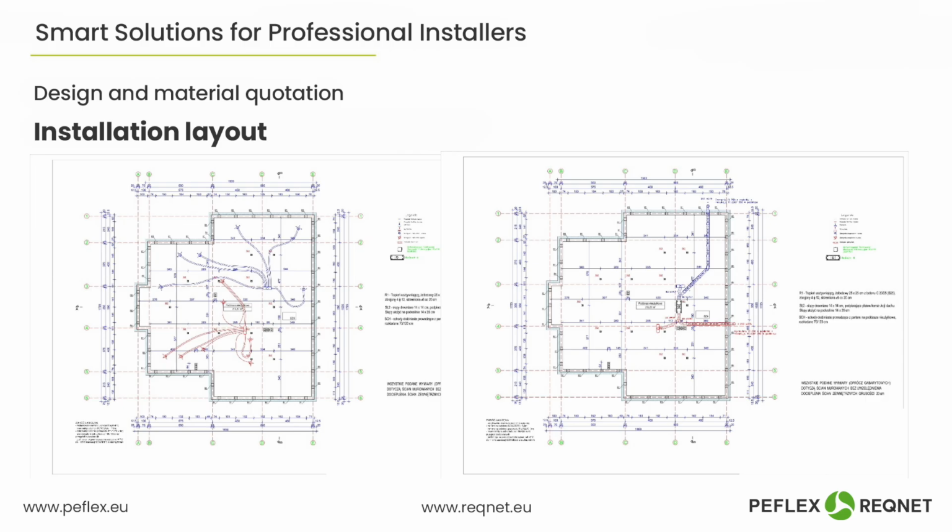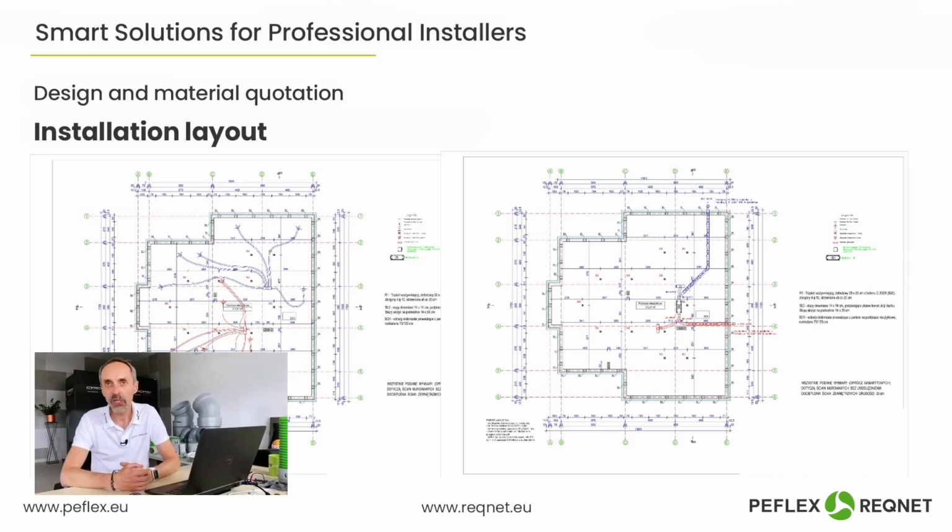In the design, we receive a diagram of the installation, meaning a layout of the individual ducts, for example, from the distribution box to the living room or to the bedroom, or from the distribution box to so-called dirty rooms like the kitchen, bathroom, or toilet. And depending on the airflow, on the capacity, we select the number of ventilation ducts according to their diameter and capacity so that, in the end, at this supply point or at this exhaust point, we achieve the desired airflow.